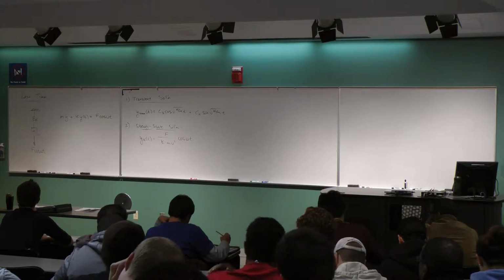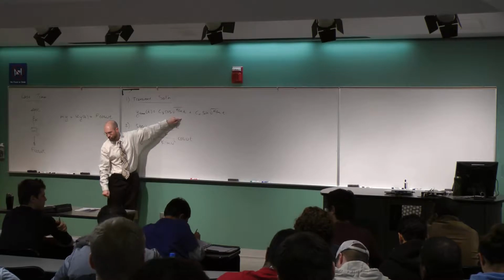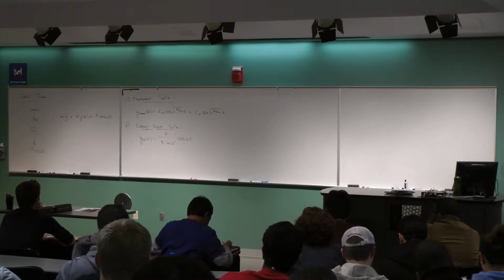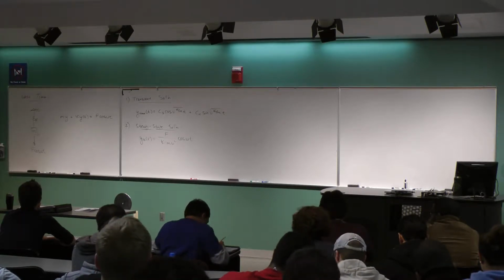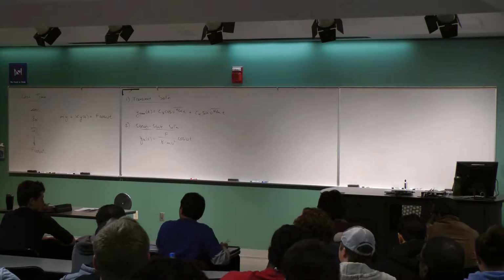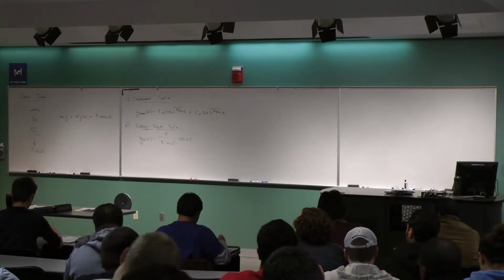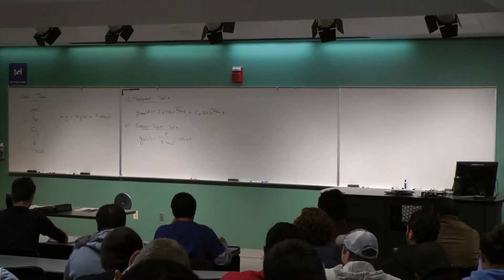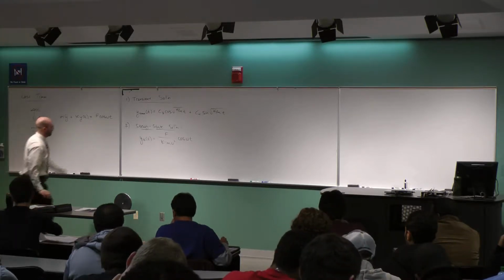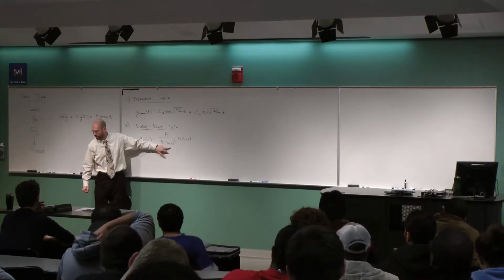We realize that the frequency of oscillation is the part that's in the transient solution, root k over m times time. Now we said, well, what if I have a mass here, and instead of it just freely vibrating like this, what if I grab it and vibrate it with some other frequency? And that frequency is omega. That could be any number. And as we developed this steady state solution last time, we said this is what the answer is,